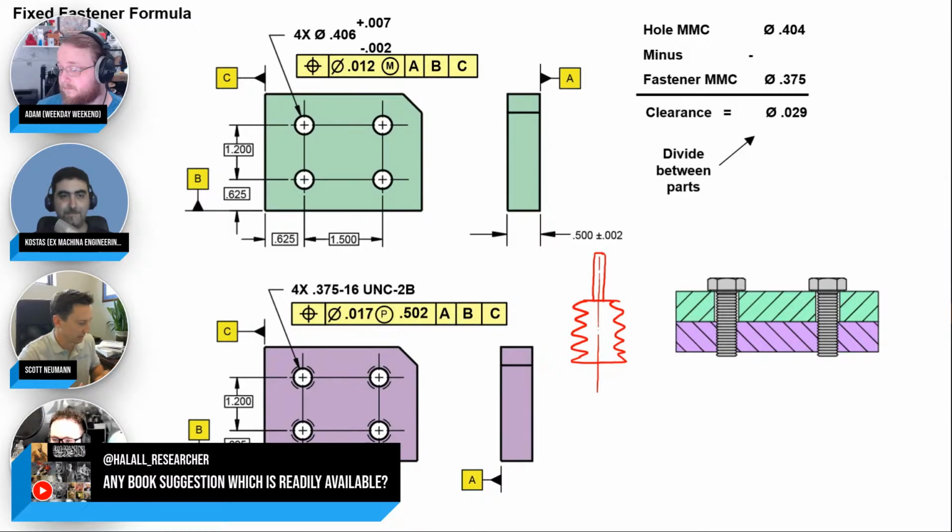Think about that for projected tolerance zone too. You're threading that thing in there, and then what's sticking out is your awesome little ground diameter on the pitch, so you can measure that. Now, the only thing with those is they can be a little sloppy, right? They can kind of rattle around in there a little bit. So some of them have slits put into them, and the slits are constantly trying to expand it in there. So when you put it in, it expands because it's got the slit in it, and that takes out the slop, and now you're pretty much centered up on the pitch. That's the axis that you care about.